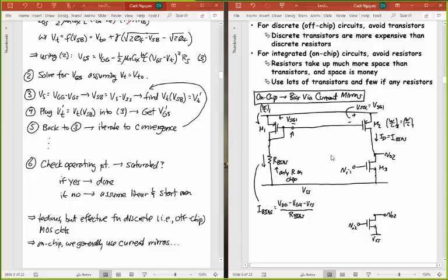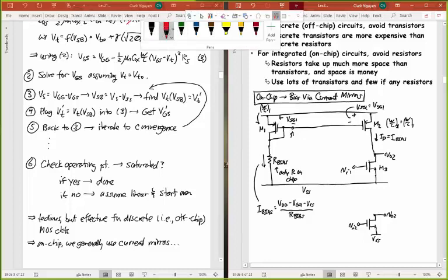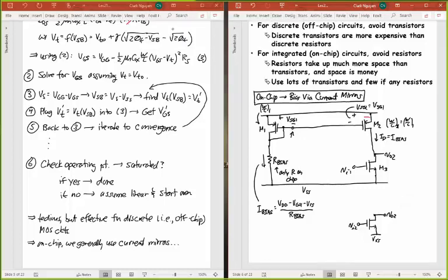This is a replica. You could say that this transistor out here is a replica of that transistor. It's got the same VGS, it's got the same W over L, so because of that it's got the same current flowing through it. Okay? And so that's how I establish this ID is equal to I bias for this transistor here. I do have to solve a nonlinear equation, but just once. And once I get that, I have this voltage, I just distribute it to all the different amplifiers on this.